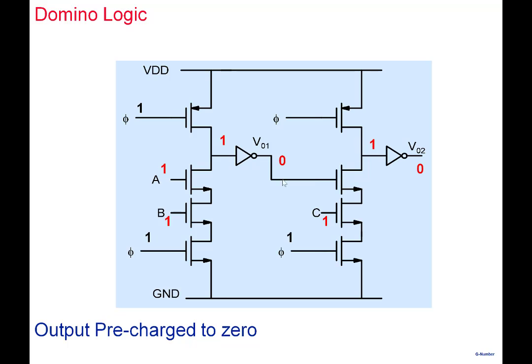Because normally, you see, what you're doing is you're pre-charging the output to 0. Now the 0 value may be incorrect, let's say. But then an incorrect value that goes to an NMOS doesn't do anything to the NMOS. Right? NMOS doesn't turn on and doesn't cause an error here. And when this value here is 0, it goes to 1, then the NMOS turns on, and then the appropriate value of the output reaches, and then the final output is also correct here.